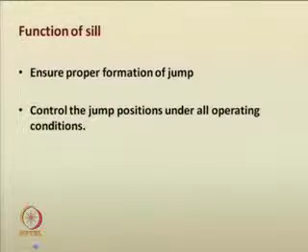So, what is the function of a sill? The sill has to ensure proper formation of the jump within the stilling basin, and also to control the jump position under all operating conditions. The flow in the channel may vary, the amount of discharge may vary, so you have to ensure that the jump occurs at that particular position itself. For those conditions also, control of jumps is required.